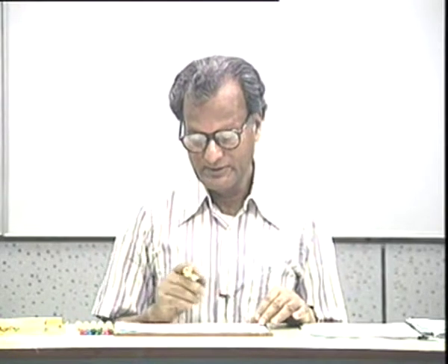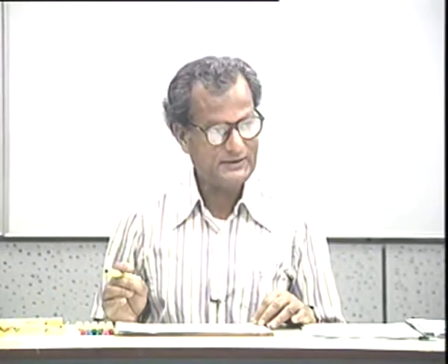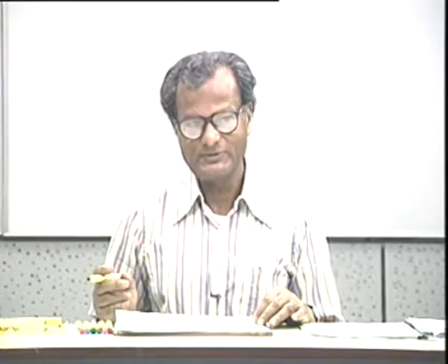We're going to start our discussion on wide banding techniques, and we'll devote quite a few lectures to this topic. Today we shall discuss the introduction to wide banding techniques and how inductors can be used. Obviously, if you want to use inductors, it cannot be an integrated circuit. It has to be a discrete circuit or an IC chip with an inductor added from outside.